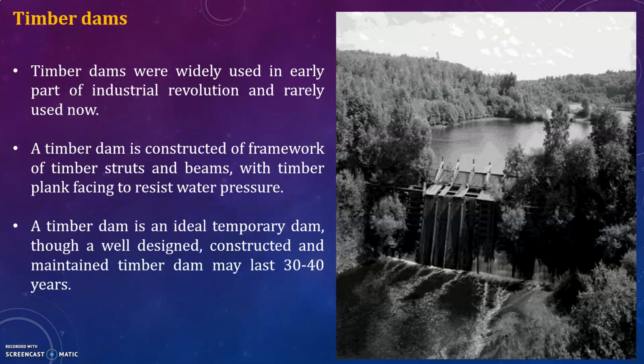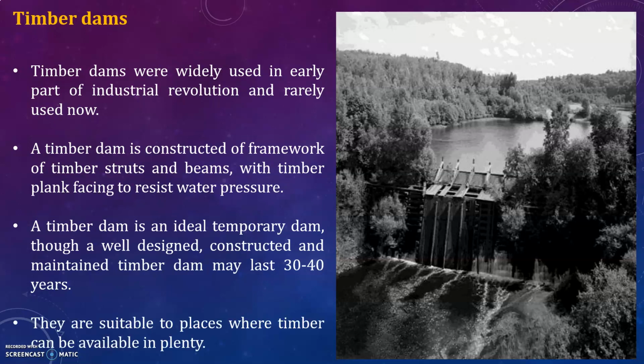Though a well-designed, constructed and maintained timber dam may last 30 to 40 years. They are suitable to places where timber is available in plenty. Timber dams are normally found to be of three types. The first one is a frame type, second one is a rock-filled crib type, and third one is beaver type.